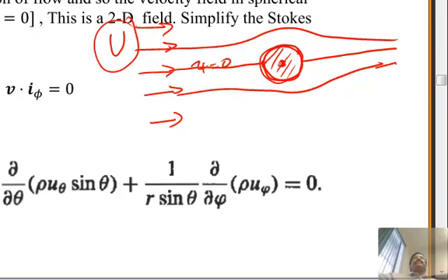You design your parachute so that you have a large area and it offers a lot of resistance, a lot of force. In an undergraduate course, you might have done these kinds of problems where you design a parachute, but the drag coefficient is given to you. For a parachute, the drag coefficient is this. Then you can set up a simple equation between the force and the velocity. Here we are going to solve for that relationship analytically for this particular problem.